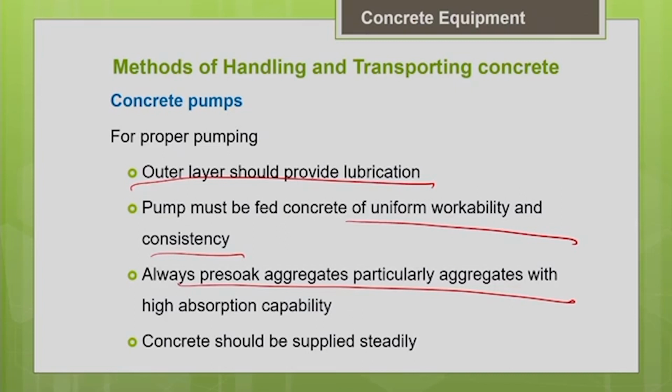It will absorb the water well. So after you put it in the concrete, it won't absorb your mixed water, and that won't affect your pumpability or the workability of your concrete. So this kind of preconditioning is needed. Then another important thing is pumping is the best option when the concrete is needed on a steady basis. You need a steady supply of concrete, then pumping is the best option.